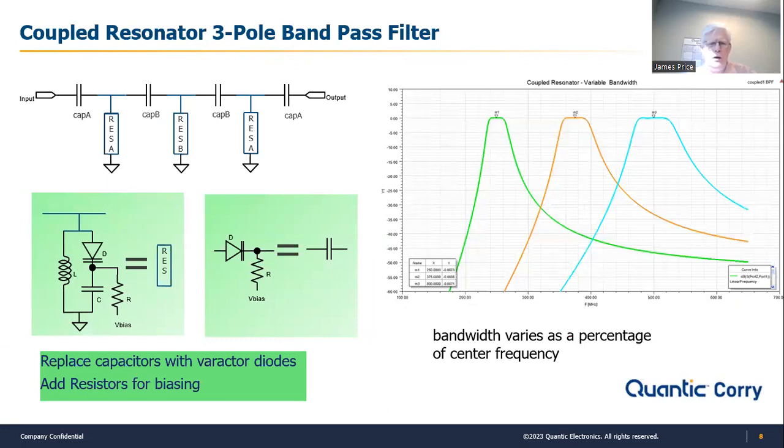So this is really showing you how you would use these resonant structures to make a filter. I referenced a book at the beginning. The author of that book goes through in great detail how to create a circuit like this. Basically, resonators A, B, and C are what you're seeing down there in the lower left: the varactor in parallel with an inductor for a parallel resonance circuit.